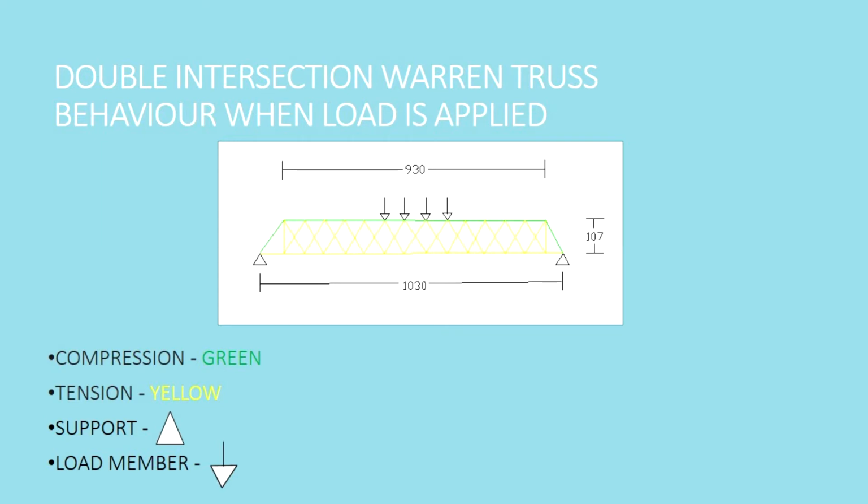For the testing results, I used the blue chair as the support. Next, I put a load, which is a brick with 2.6 kg, on the bridge slowly. After that, I put another load on the bridge and the bridge begins to collapse. Hence, this bridge can only hold up to 5.2 kg load.